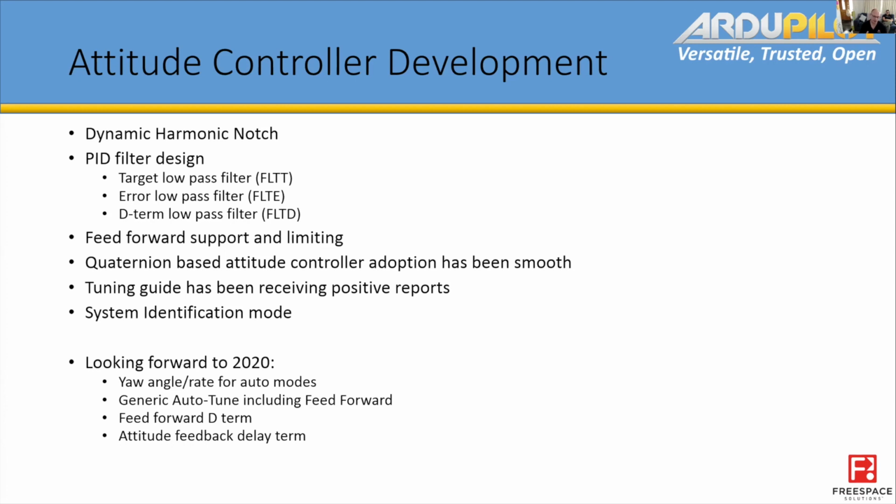And what I'd like to be able to do is have auto tune take the PID object and maybe a parameter that's set at compile time in the PID, or something that the user sets in the PID, that sort of says what sort of tuning approach to take for that PID. Auto tune then goes through when it's handed that PID, when you pull the channel 7 switch or change mode to auto tune, it reads that and says, okay, this is the methodology I need to use for this particular axis.